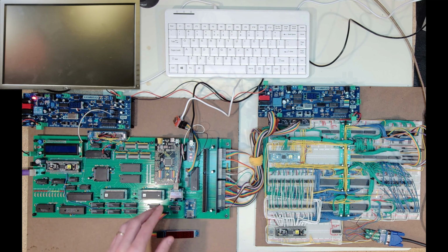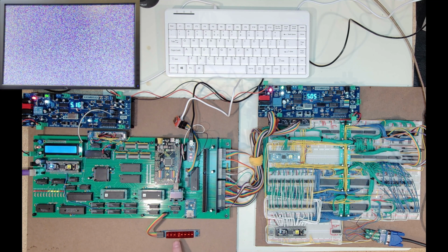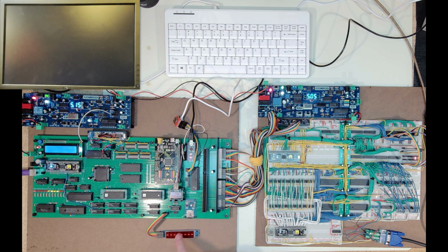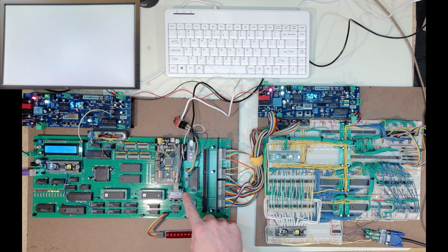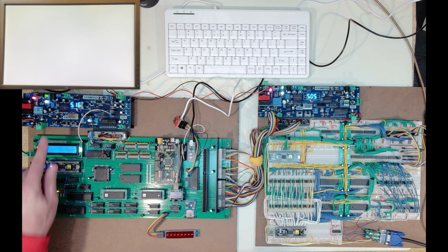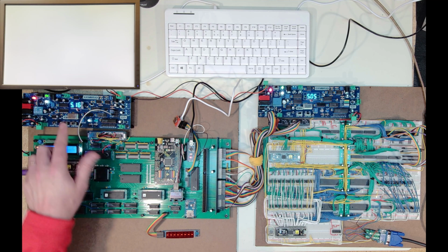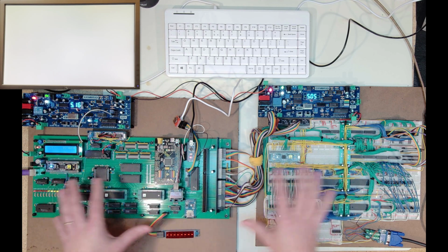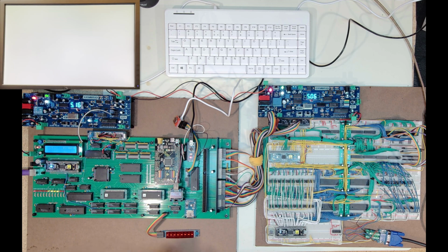So system's off. I'm going to go ahead and turn it on, and I'll probably go through this a couple times, but it's doing a normal computer RAM test. You can't read this, I know, but that is after the RAM test doing a VGA register test and then a VRAM test of that first 64K of frame 0, and that passed. So that gives me some confidence that I'm getting over here and back. I should maybe comment, I am running a 32 megahertz oscillator, which means 16 megahertz is my overall system bus, and then the processor internally will be running at 8.